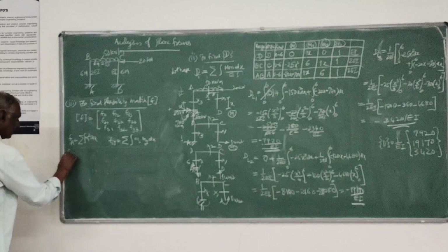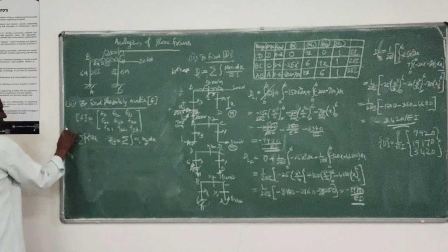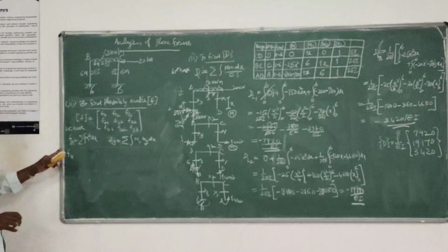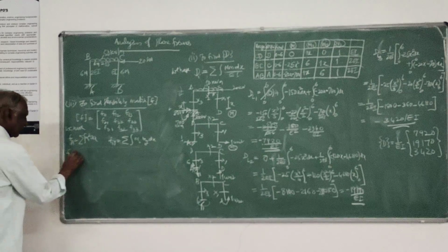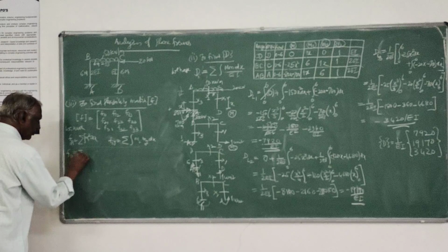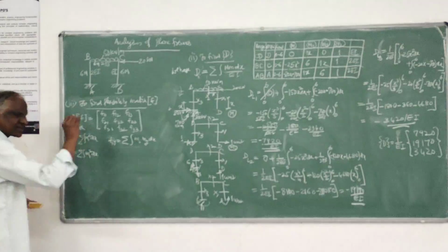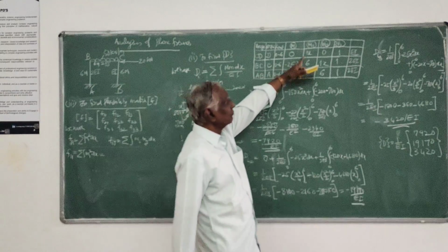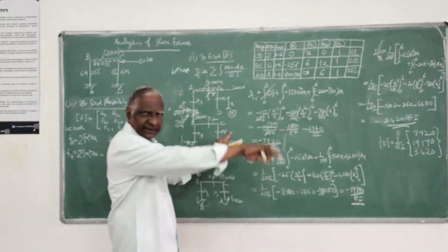Now I will find out F11 first. This coefficient Fij is given by this. So F11 is nothing but sigma of integral m1 square dx. That is, you take here m1 square dx. x square for this member; for the other it is 0 for the entire structure.